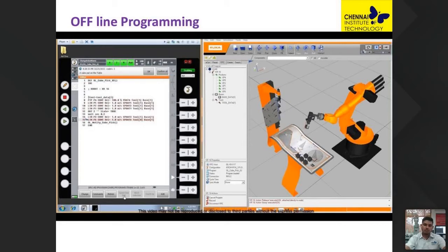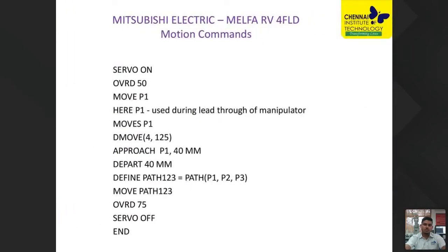After this programming is done, we have to once again go on with the programming in the online mode. We have to check it in T1, that is teaching mode 1, where the maximum velocity is 10% of the full velocity. With that we will be checking it. Later we will go for T2, slightly increasing the velocity, then we will check it, and finally we will go to automatic mode. So this is the method we will follow, one by one, for each and every concept.